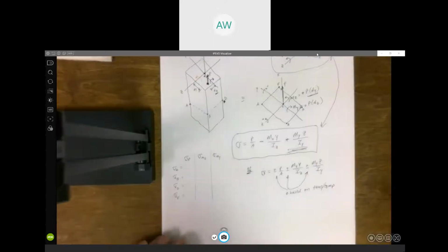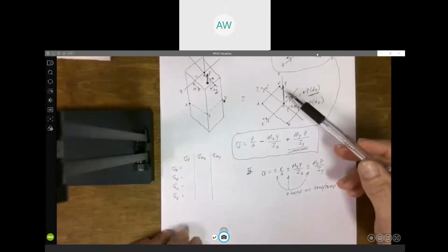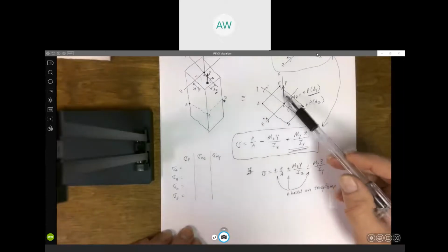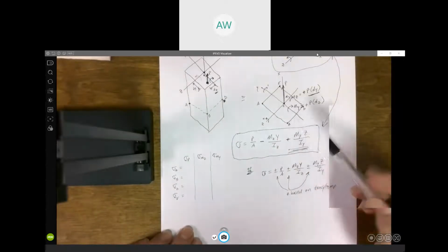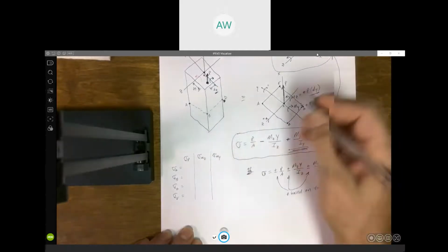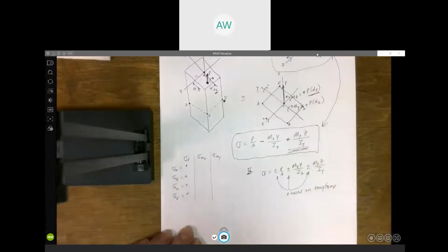So first up, axial force P. Obviously, it's acting up, it's pulling on this thing, it's in tension. So that axial load P is causing tension everywhere. It's causing tension on that entire cross section, so it doesn't matter which point you're at. All of those P over A terms are going to be positive for any point on that cross section.